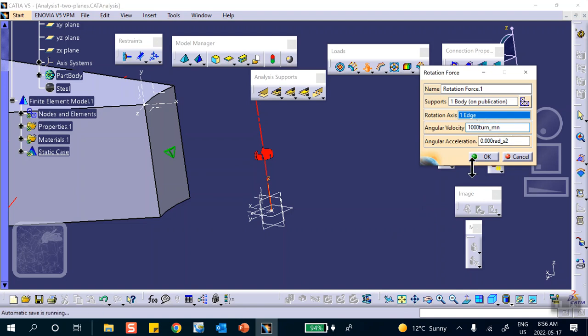Okay. One last thing. In the last box, it says what is the angular acceleration. If it's going at a constant speed, angular acceleration is 0. Whereas this was a disk that starts from stationary condition and builds up speed. To reach that, of course, there is an angular acceleration. So what you do is you calculate the stresses at the time where the acceleration is such and such. But for me, I'm assuming it has reached the steady state and is turning at constant speed. 0 angular acceleration, which means constant speed.